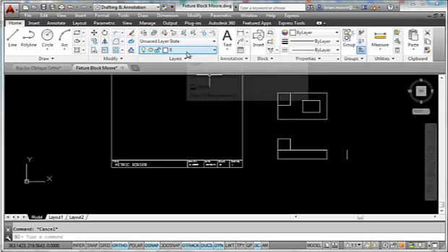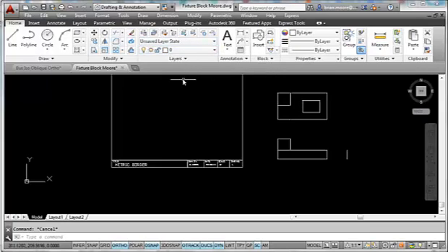It should just check your dimensioning. So while I'm at it, I'm going to get started on dimensioning. To do that, I need to put the dimensions 10 millimeters times the scale factor away from the object, and it's a 1:1 scale drawing, so it'll just be 10 millimeters away. In an orthographic drawing, we place the dimensions between the views wherever possible, and we don't repeat dimensions. So I'm going to O for offset, type in 10. And I'm going to give myself some lines to work with.